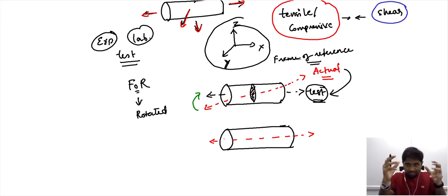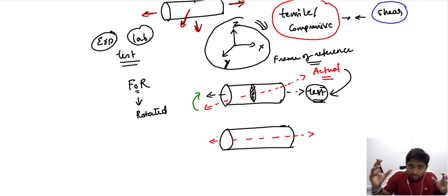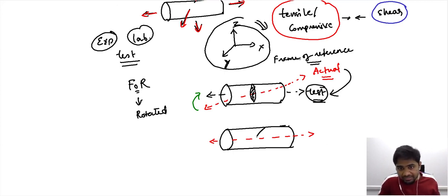Now we have introduced a frame of reference, and all we did was rotate the frame of reference in such a way that the actual loading condition aligns itself to the test direction that we are familiar with. However, when you rotate the loading direction, what also rotates is your area of interest. The area that you have been considering so far also rotates.